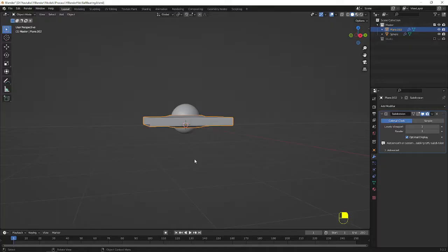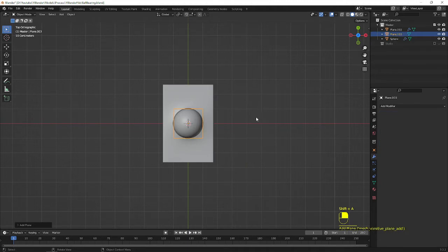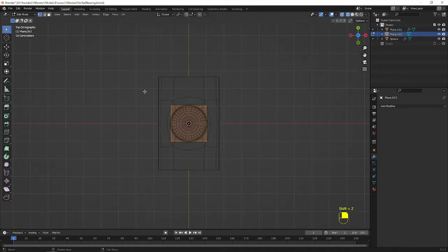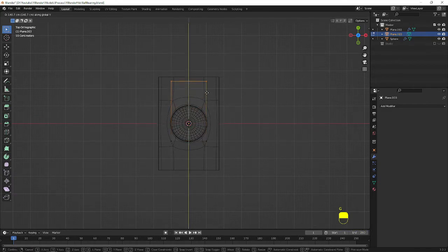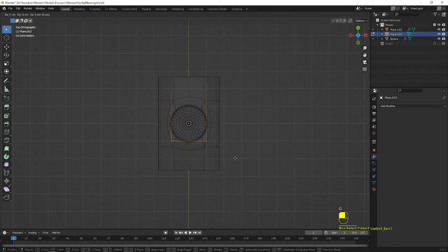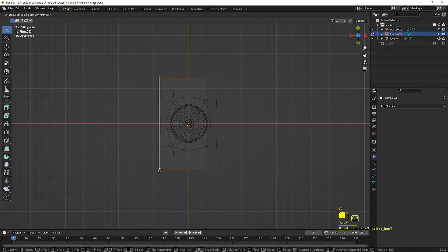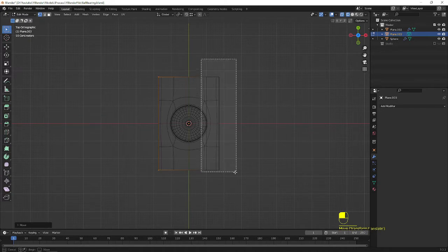that is the bottom one. So I am going to the top view and press Shift A and create a plane and go to edit mode, go to the wire selection. I am going to select this, GY and go to this option and select the vertices and GY and use the Ctrl key to snap the edges. So same way GX and I am using the Ctrl key to snap the corner.